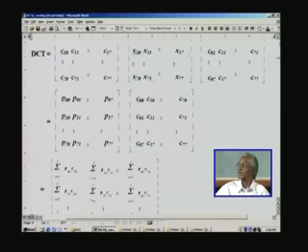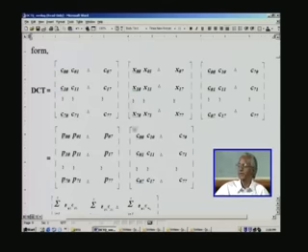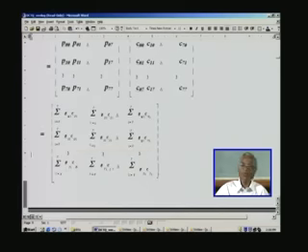And now the crux of this algorithm is here. As you are evaluating this DCT coefficient, concurrently you can also evaluate this coefficient, because it is quite free to execute concurrently. Concurrently means simultaneously. So that is the contribution of this algorithm. Thereby you save time, and the whole thing can be pipelined in such a fashion that you will get the output at the rate of one coefficient at every clock pulse.